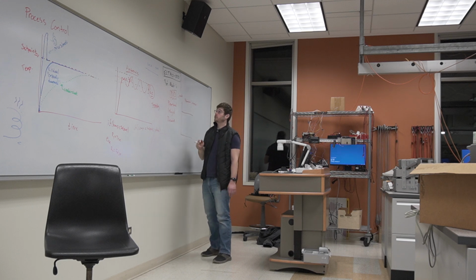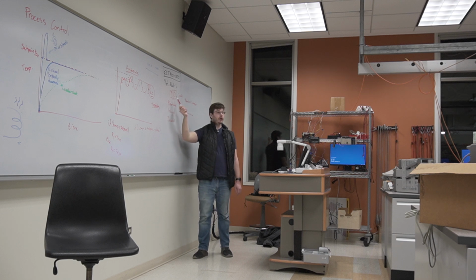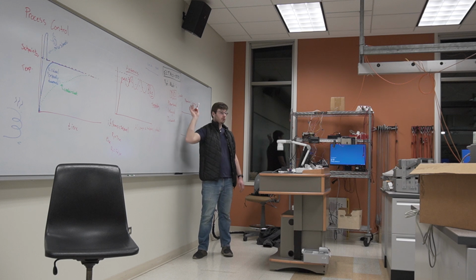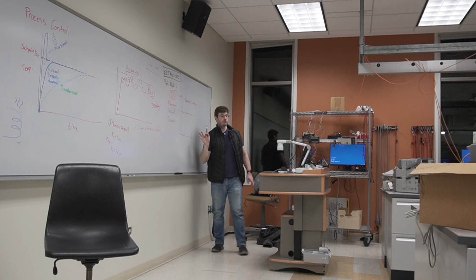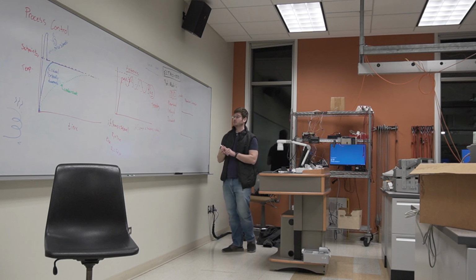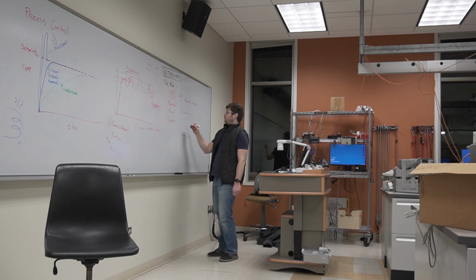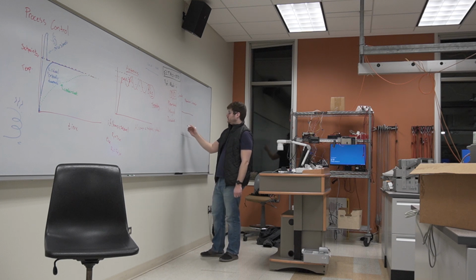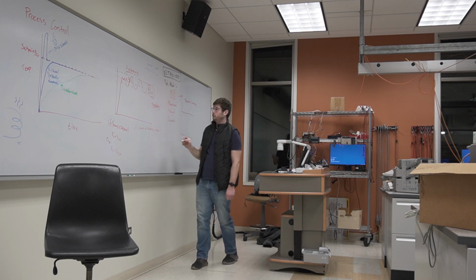but you don't strictly have to have each of these three components. You can have a P controller, you can have an I controller, you can have a PI controller, you can have a PD controller. You can eliminate selectively each one of these, and I'm going to show you how to do that. But each of them does something slightly different. Okay. So again, what a proportional controller does is it tries to correct for error in a proportional way.